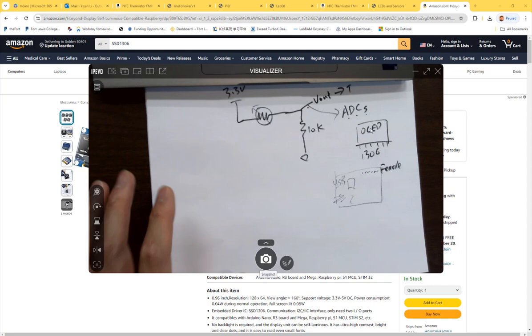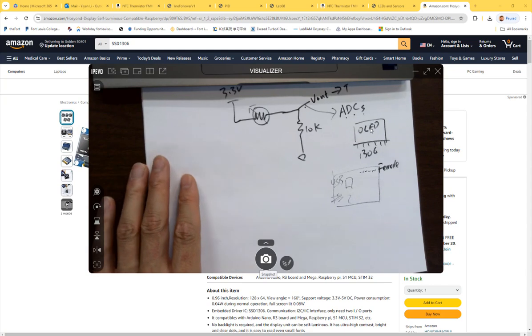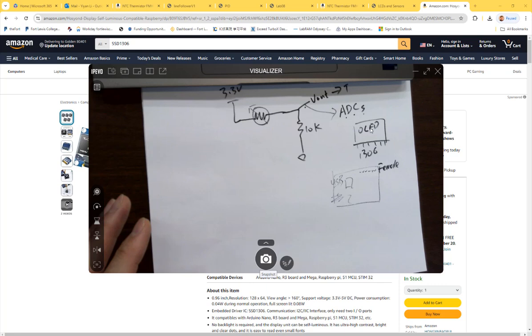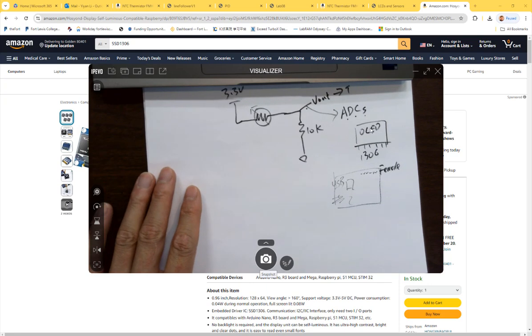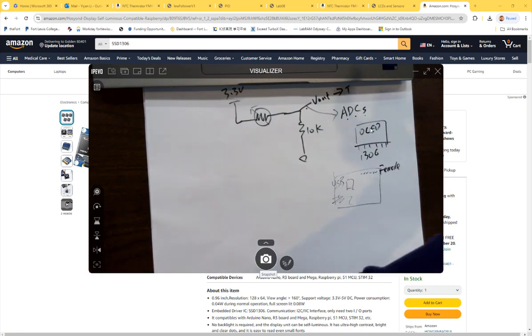I saw a bunch of libraries on Arduino, like Adafruit. Is that the one? That's a standard one to use. I use that one. How do you use them? I don't know if you can use it with PIC. It could be because there are several different things. So the Adafruit library is mainly for the character formatting, but it's probably not for the SPI library for PIC. I looked it up online, and the guy's like, just do it in MCC. I'm like, where? Oh yeah, there's MCC. It's MSSP2. Oh, okay. Yeah, there's an SPI MCC module.